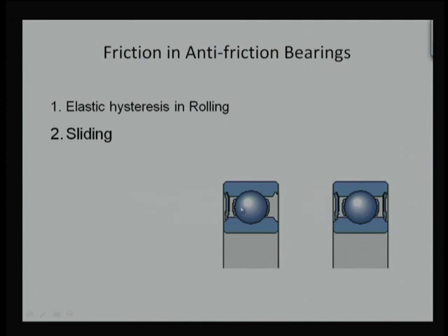Even though there is a touch, the rolling action will not be there, it will be more like a sliding action. Similarly, there is an inner ring, and we know that to support axial load to some extent, we use some sort of curvature, and a slight change this side, a slight change that side is going to introduce some sort of sliding. In pure rolling cases, with pure radial load, there may not be any sliding, but we know there will be some sort of axial force, it will be shifting, and then pure rolling action will not be there, some sort of sliding will occur.